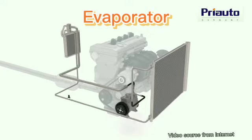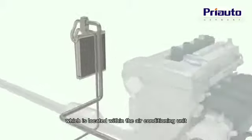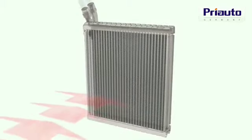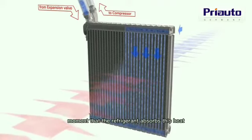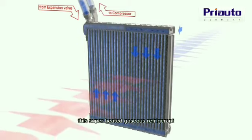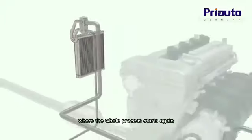Low-pressure mist refrigerant now flows into the last major component of the air conditioning system, the evaporator, which is located within the air conditioning unit. The evaporator consists of a tank, tubing, and fins that are exposed to the air in the passenger compartment. Therefore, heat from the air is able to transfer to the fins, and it is then absorbed into the refrigerant mist. And at the exact moment that the refrigerant absorbs this heat, it vaporizes and changes back to a gas. This superheated gaseous refrigerant then flows from the evaporator and back to the compressor, where the whole process starts again.